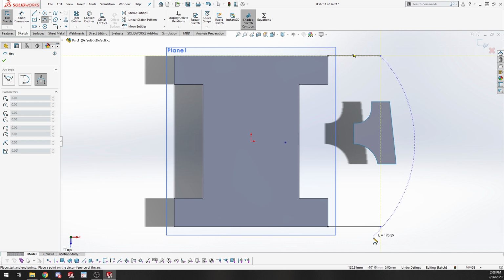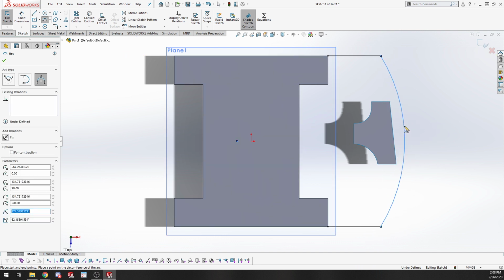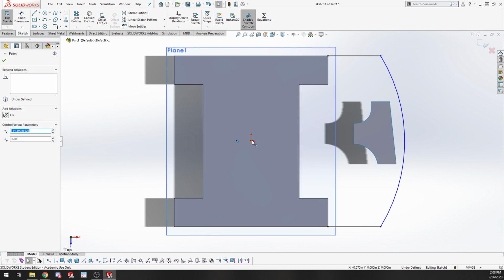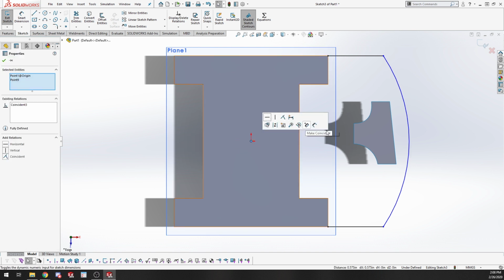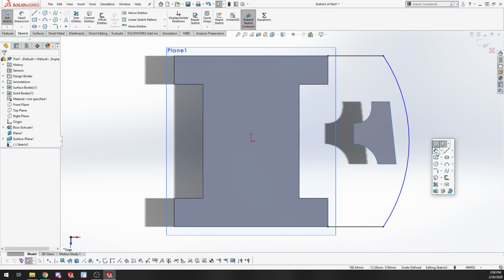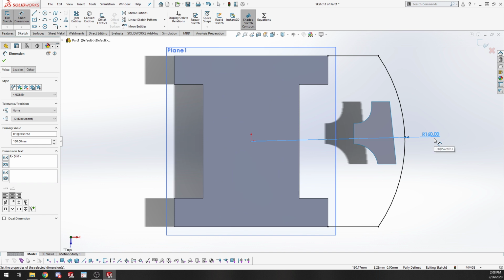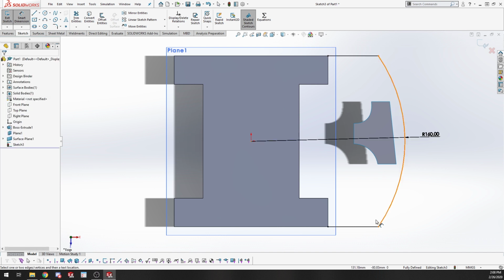if you remember, one of the things with the steering wheel is that the outside diameter is what defines it. So what I want to do is make this arc centered at the origin, and then give it some value. This is going to be my outside diameter. It's going to be 160 millimeters in diameter for our steering wheel. That's what's important, because as I spin it around, I want to make sure that I have clearance for the driver's legs. And that outside edge being an arc is what's important here.